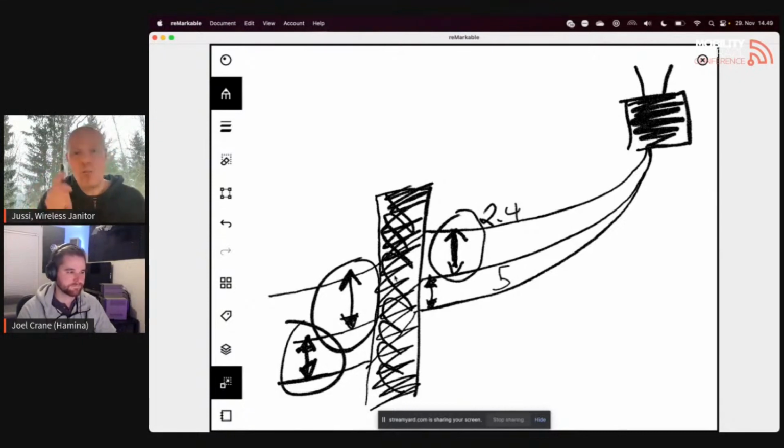So these days you definitely want to also design for 6 gigahertz using predictives, just to make sure that you're on the correct page. But when you design for 5 gigahertz, I wouldn't see it as a humongous risk today. Your 6 gigahertz is very likely to work at least decently. What would you say, Joel?